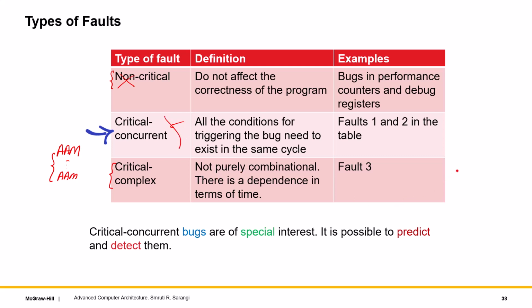Well, the first thing is that you need to collect all events of interest. All events of interest are called signals. Now, how do you know what to tap? Well, you can look at historically things like L1 miss, L2 miss, all architecture specific things, right? So all of those can be tapped, and you just have to pray to God that whatever is a real condition, the signals for that are within this set.